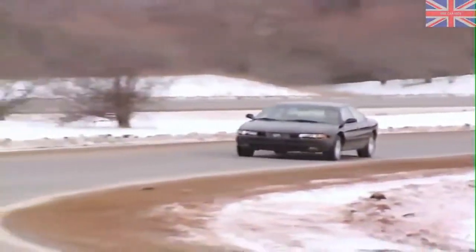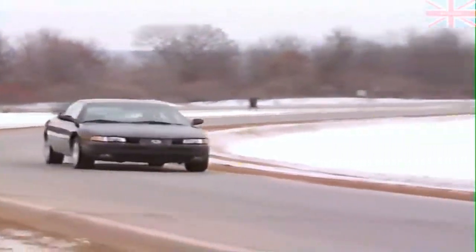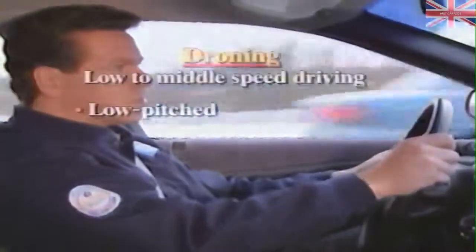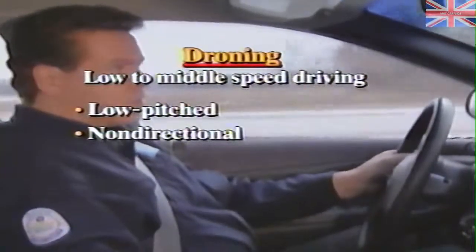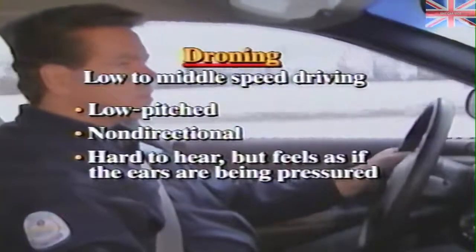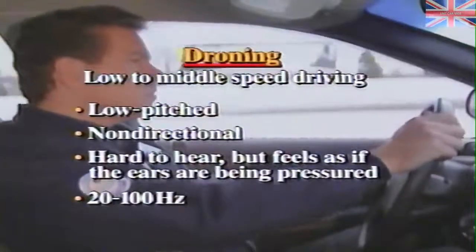Droning, another common noise, is equally challenging to troubleshoot because it can happen at any time. During low-speed to middle-speed driving, droning is a low-pitched noise that is non-directional. It seems to come from all over. It's hard to hear as a sound, but it feels as if your ears are being pressured. The frequency is generally 20 to 100 hertz.